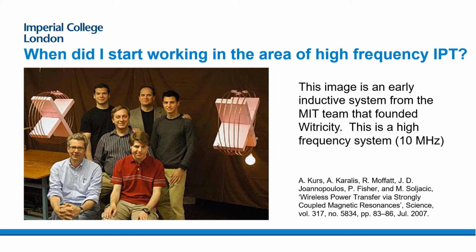Now, I know there's a lot of work that happened in inductive powering obviously before this work was published by these guys at IPT, but I thought it was quite a striking photo, and in particular you can see here in this IPT system that there is a very considerable distance between the transmit coil and the receive coil that's obviously big enough to fit the whole team in between the coils. And I thought that was quite an impressive demonstration. One of the interesting things there is this is actually what we would refer to as a high frequency IPT system. It's operating in this case at about 10 megahertz.